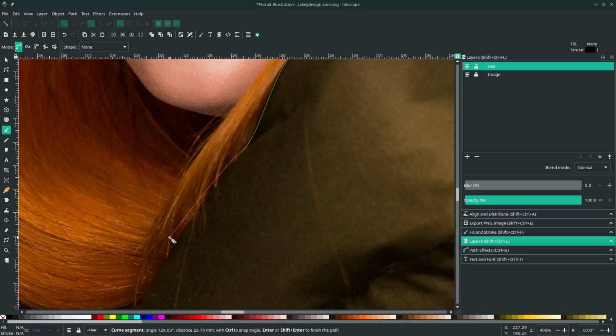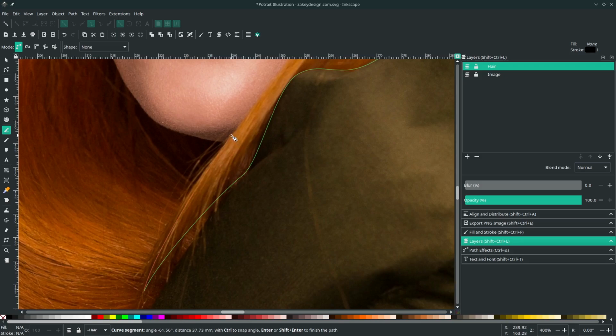And on here, we're going to lock the corner. Just drag it like this. And hold shift to lock the corner and release. So you see it makes a sharp corner to this. Or you can see my previous video how to create flat illustration from photo, because we're going to use many lock corners in this tutorial. Right, just continue.